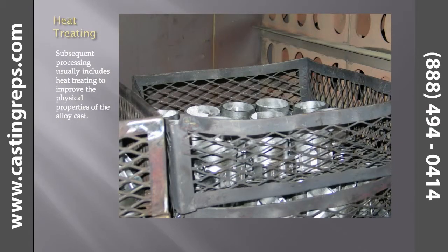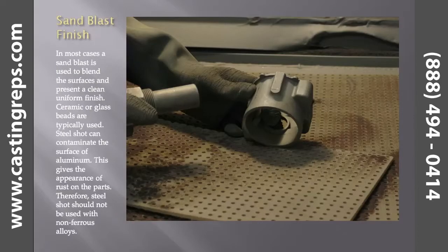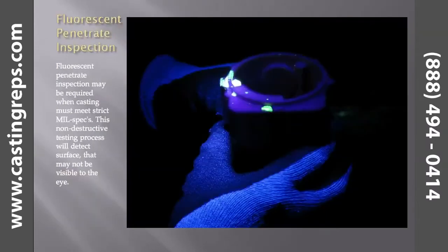Heat treating. Subsequent processing usually includes heat treating to improve the physical properties of the alloy cast. Sandblast finish. In most cases, a sandblast finish is used to blend the surfaces and present a clean, uniform finish. Ceramic or glass beads are typically used. Steel shot can contaminate the surface of aluminum. This gives the appearance of rust on the parts. Therefore, steel shot should not be used with non-ferrous alloys.